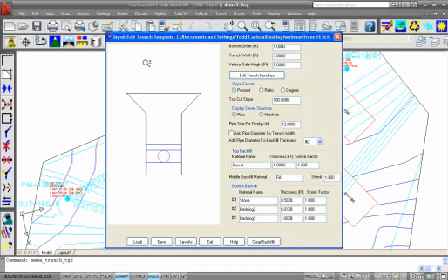Right. What this gives us is complete volumes for the stone, bedding, and gravel that we've defined here, a lot more sophisticated than just looking at the plan and estimating by the distance of the pipe, because the depth of the pipe is changing, so some of these materials change depending on the depth and width of the pipe.